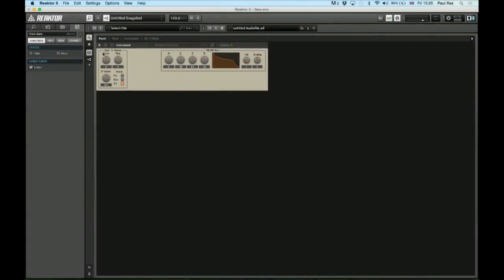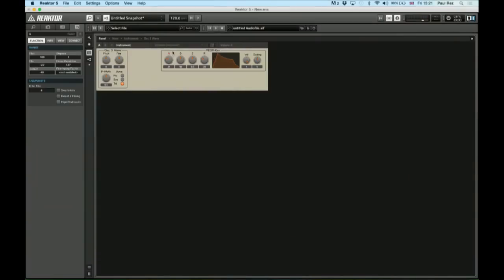So now if we go back to our panel view, we can start looking at some of the controls and what we have just with this very basic setup with one oscillator. Very important, you need to lock the panel before you start changing parameters. Yeah. If you don't, things are just going to move around, and it starts getting very messy. So make sure you take that edit control off to lock the panel. The first thing I'm going to look at is just the ADSR. So just by changing the attack and release. And it's already polyphonic. Yeah.